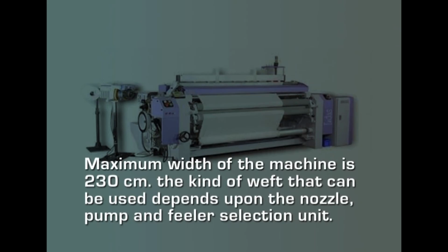You cannot weave very heavyweight fabrics on this, or use yarn which is heavier in weight, because it will not be propelled through the jet of water from one end to the other end. Maximum width of the machines is 230 centimeters. The kind of weft that can be used depends upon the nozzle, the pump, and the feeder selection unit.